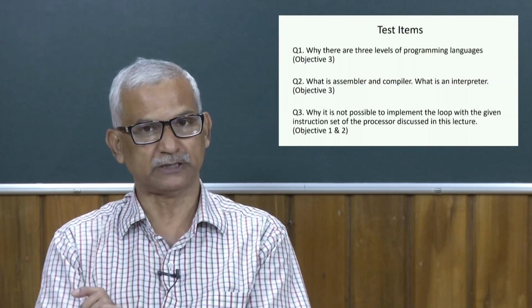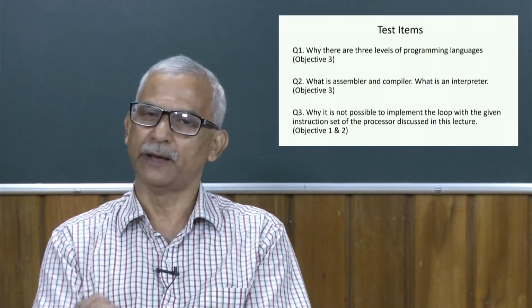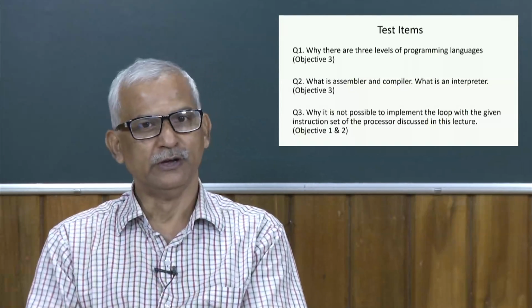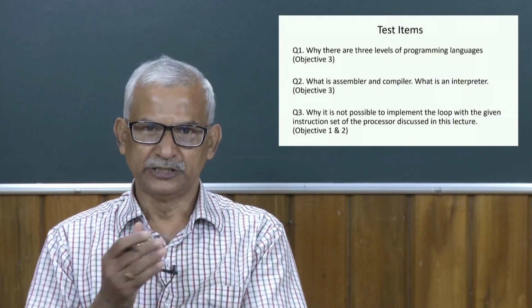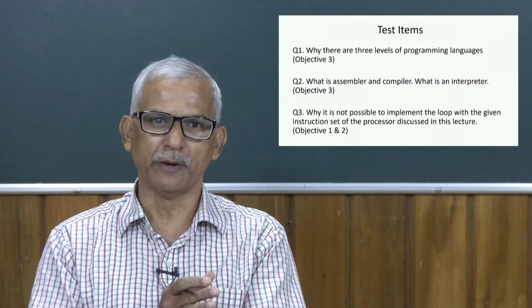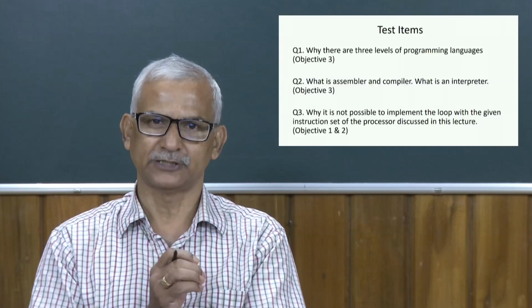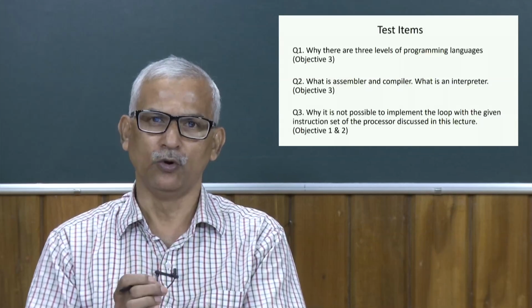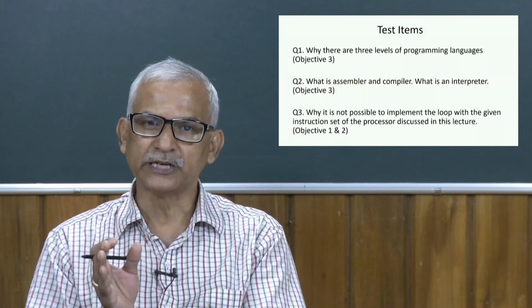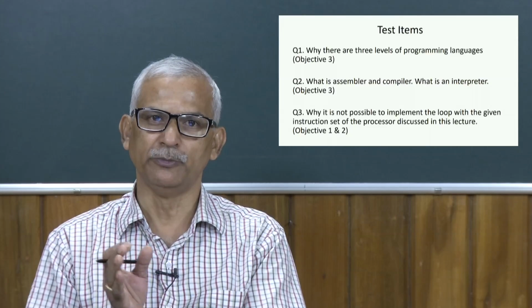That means you must remember the code of each and every instruction, which is not possible, always you have to take a reference. But instead of remembering instruction numbers, it is slightly easier to remember some code like add, subtract, multiply, load, store. So, we are giving a code to each and every instruction, which is known as the mnemonics code.